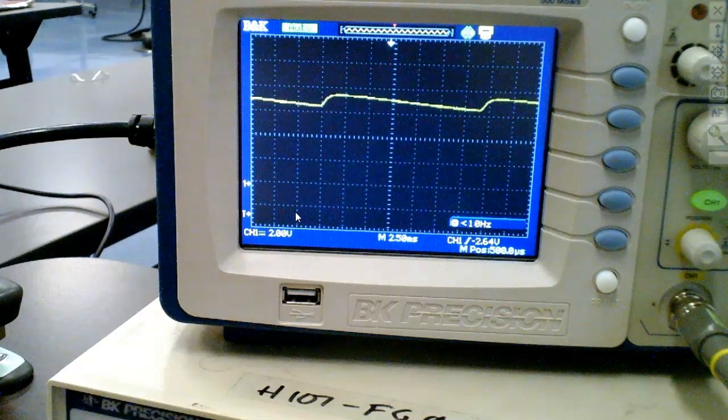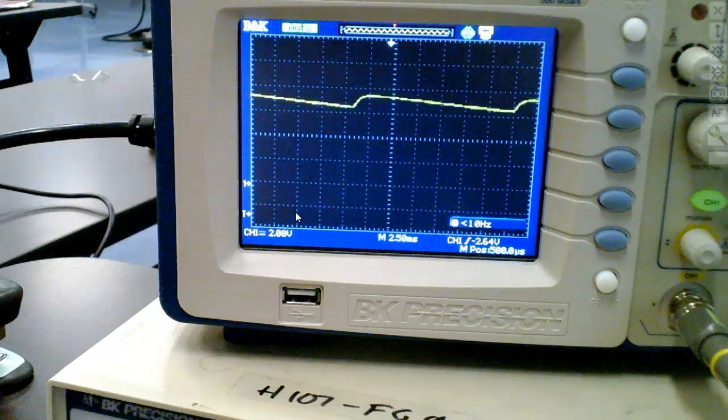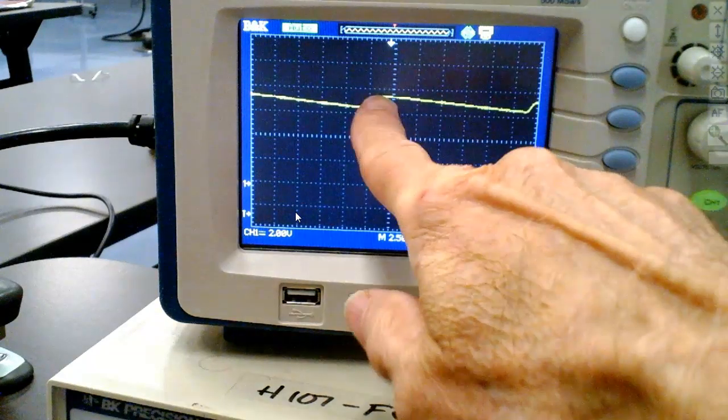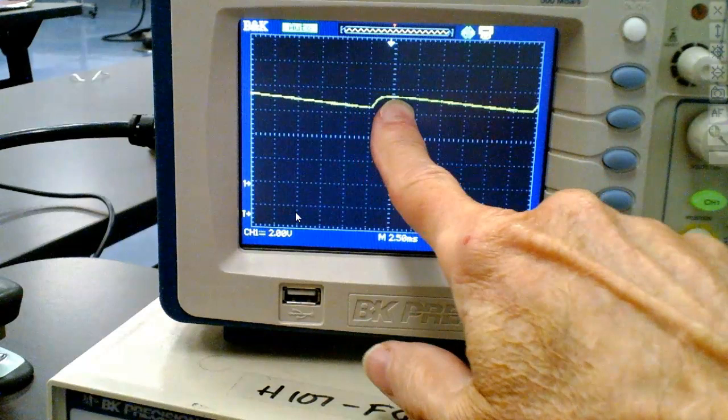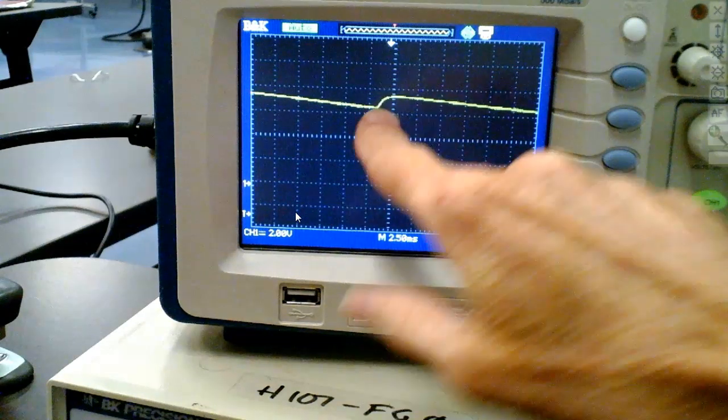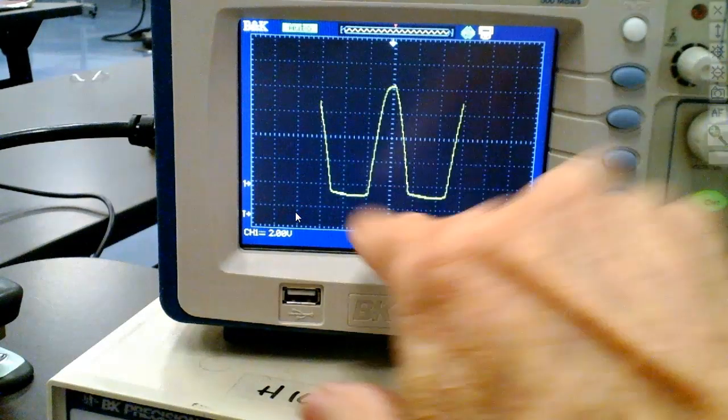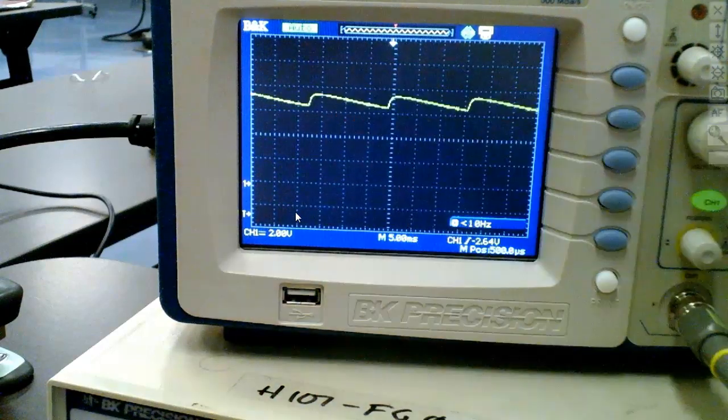So the less load I have, the capacitor doesn't have to run the load, right? So the capacitor's literally running the load during that amount of time. So it's just like a battery, but it discharges really fast. If I loaded it too much, then our output would go way down, right? You understand that? But you can actually see the slope of the capacitor. You can actually see that the capacitor is running the load through this time right here. And what happens when you charge on the next